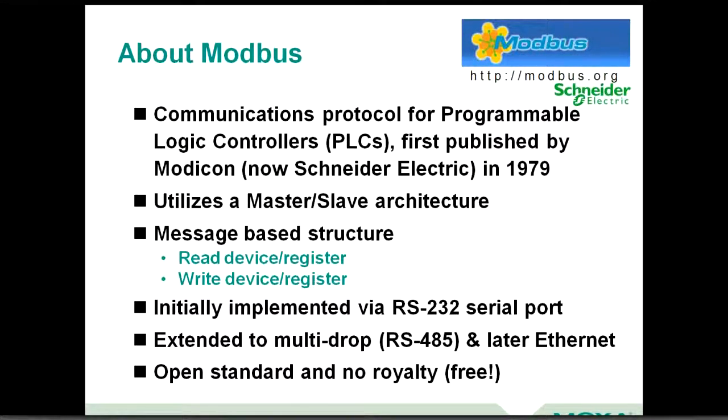They had some bright ideas to not just keep this proprietary, but actually make this available to the public in 1979. And that's really become the de facto standard for communications, and it's why we see so much of it still present today. For those of you not familiar with it, it utilizes a master-slave architecture, meaning that one device is going to be requesting information from others in your system.